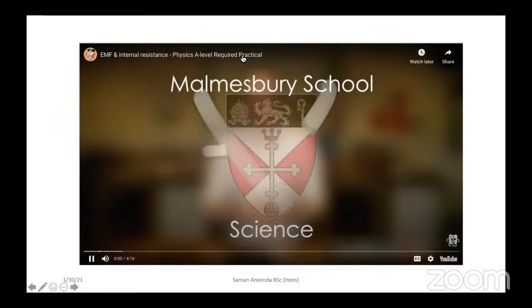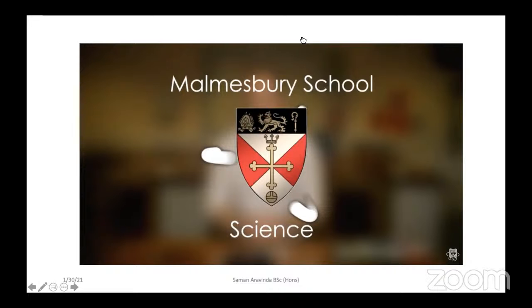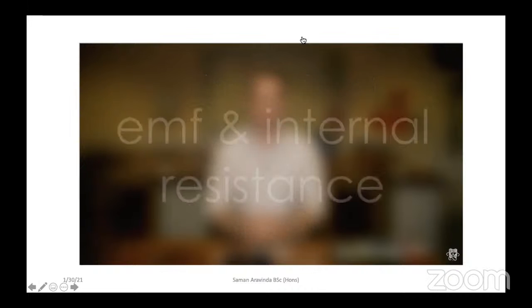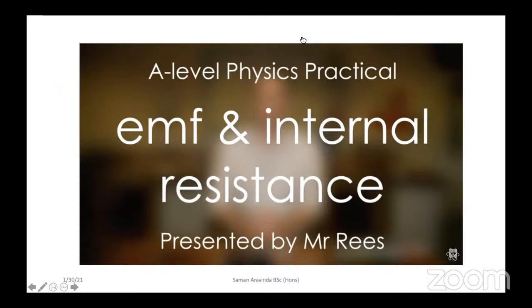Hi, this is Mr. Reese from Malmesbury Science, and I'm going to show you how to do the A-level physics practical, how to find the EMF and internal resistance of a battery. So batteries provide an EMF, that's electromotive force. You can think of that as the total voltage that the battery can output. However, batteries are not perfect conductors, so they have a little bit of resistance inside of them. So we can model a battery as a perfect battery with a little resistor inside as well, and we're going to call that the internal resistance.